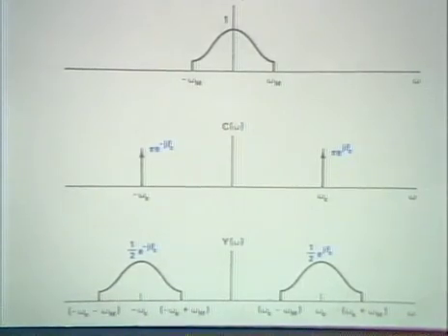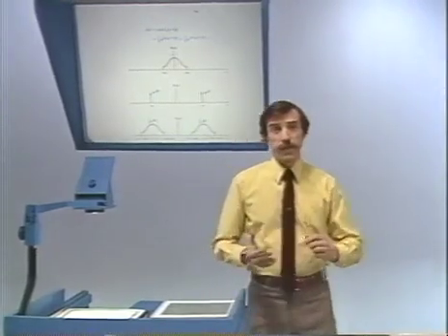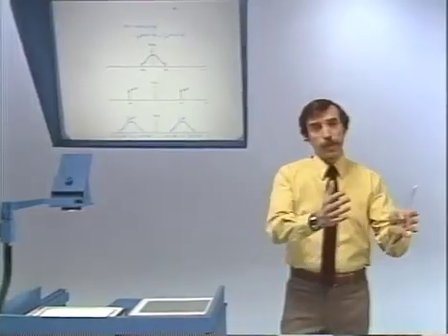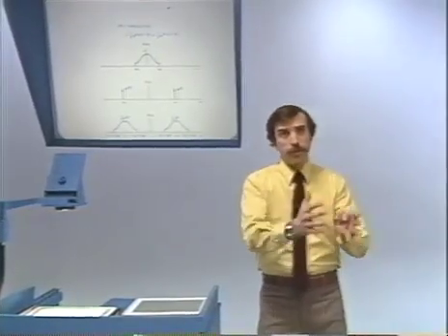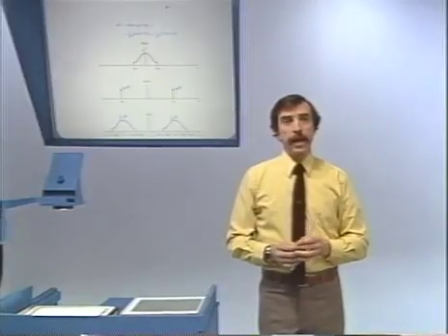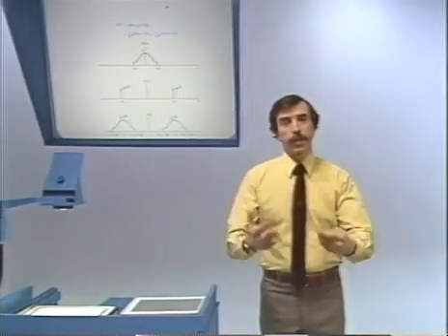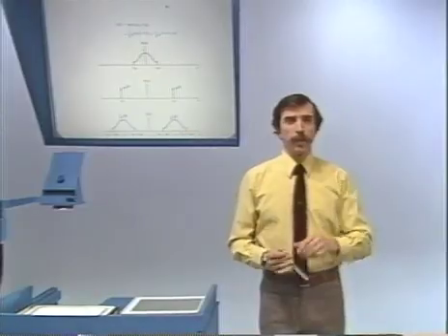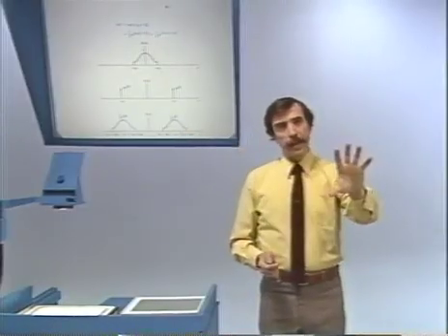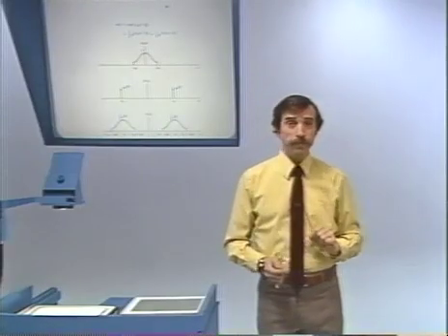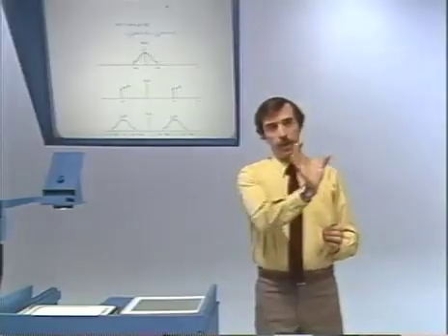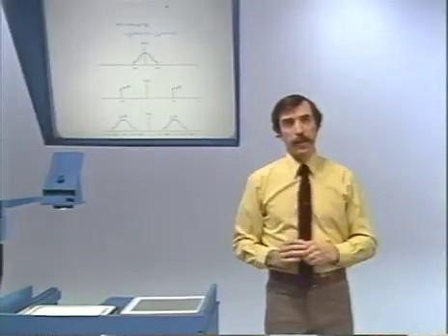Okay, well, now what's happened is that with a sinusoidal carrier, we've moved the spectrum to both plus omega c and minus omega c. And now if we want to get the original signal back again, what we would like to do somehow is move that spectrum back down to the origin. In the case of a complex exponential, that was easy to do. We had shifted one up, we just shifted back down.